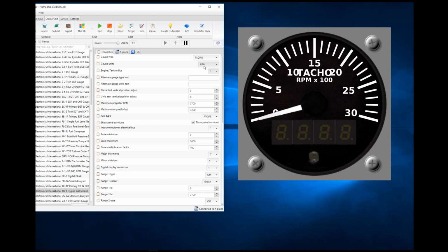And then this choice here is what gets chosen here, which is the RPM. The times 100 is another user parameter down here somewhere, where if you choose not to use a 1-to-1 scale, whatever scaling you choose, it will append onto the end of the units here. So if I weren't to choose the times 100, it would just say RPM there, and these would obviously have lots of zeros on the end of them to give you the actual real numbers with 2 zeros on the end.